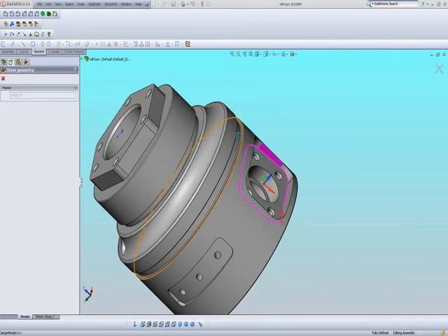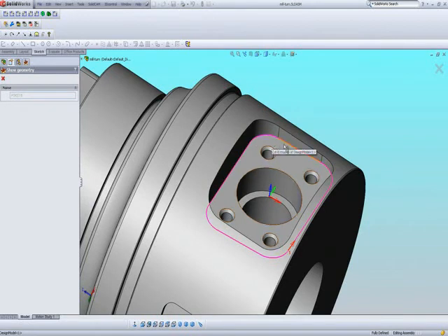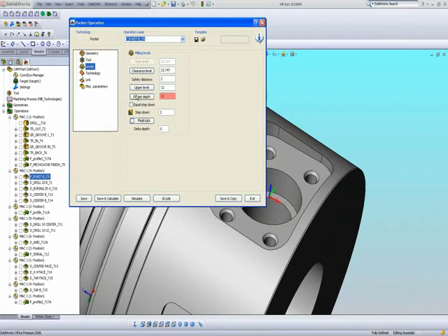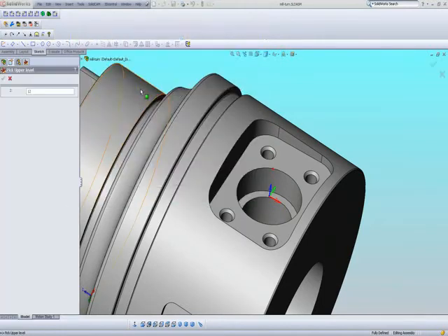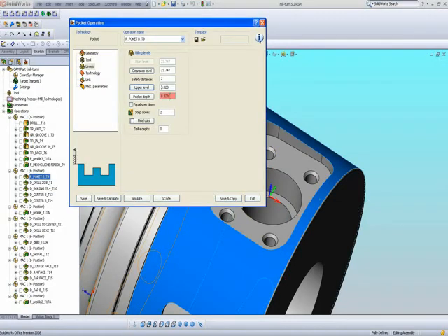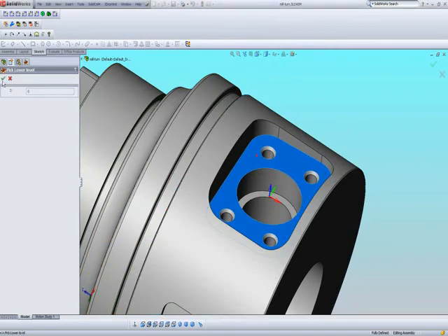My geometry in this case is this area over here, this boundary as you see over here. The tool that I will be using will be a regular end mill, 16mm end mill. My levels, my upper level, is actually taken over here, but I've made it go up a little higher than that. I've written 12mm, and my pocket depth is up until the floor itself.